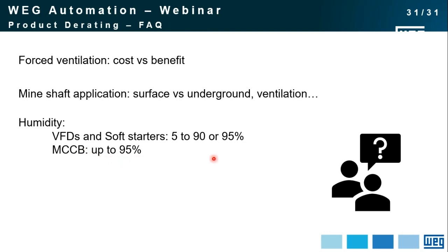But if this humidity condenses, and you have practically water in your component, that can be very, very dangerous. So how do I solve it? The idea is to use space heaters. You should first use space heaters, make sure there is no or at least low humidity in your panel, and then you can use it.